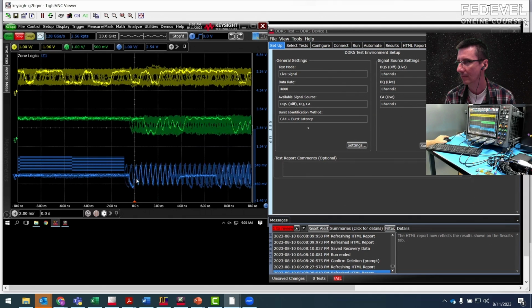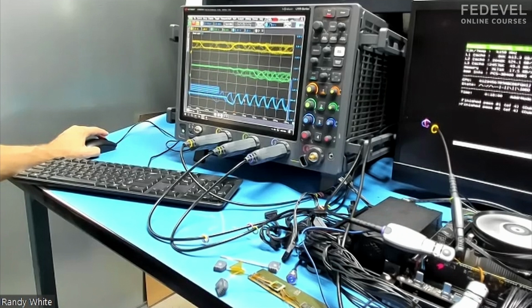Okay, I don't know if you could tell this, but there's a smaller amplitude that's riding on top of the larger amplitude. I can see it. So yes, the larger amplitude would be the read, and the smaller amplitude would be the write. And it's also not very apparent, but the smaller amplitude has a slightly slower rise time, slew rate, because it's going through the channel. DQS and DQ are both bidirectional.